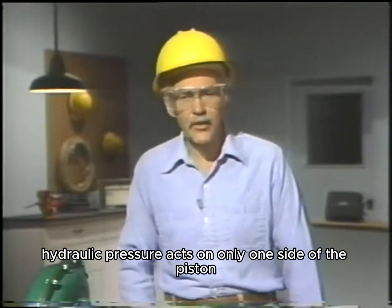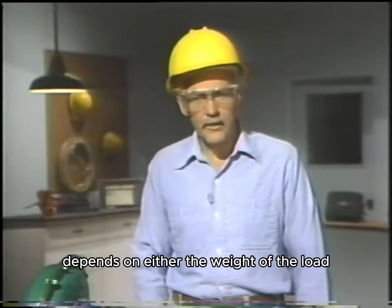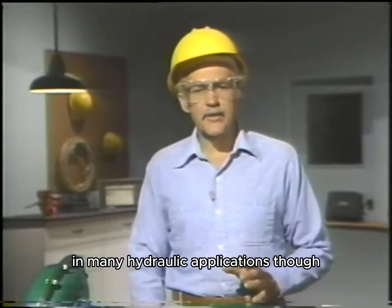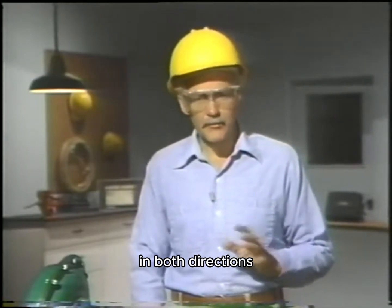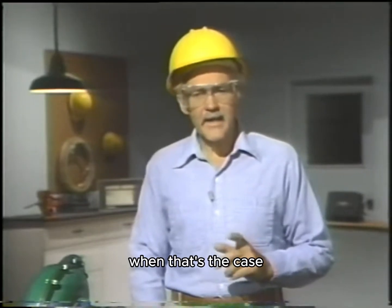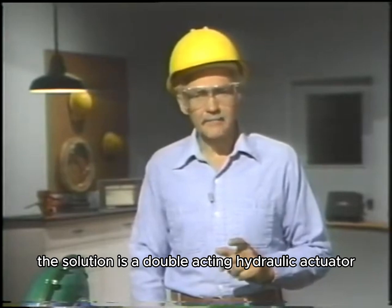Hydraulic pressure acts on only one side of the piston. Movement in the opposite direction depends on either the weight of the load or the tension of a spring. In many hydraulic applications, though, it's desirable to operate a cylinder under power in both directions. When that's the case, the solution is a double-acting hydraulic actuator. Let's take a look.